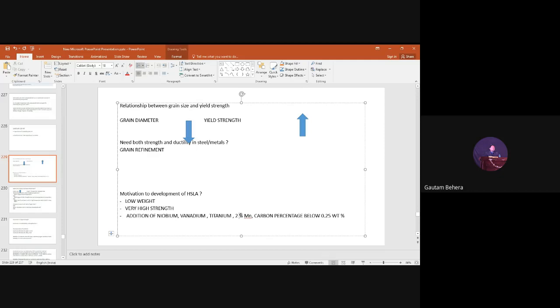Okay, Ipsita Sahu, can you answer this one? Or shall I repeat the question? You have a steel which contains vanadium, niobium, and titanium, and you are taking the steel to 912 degrees centigrade. That means austenite formation is taking place. So, what advantage will you get at that temperature if you have these alloying elements? Panda, I have already told you that they form stable carbides.